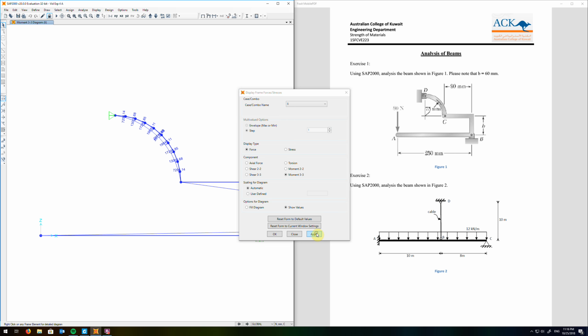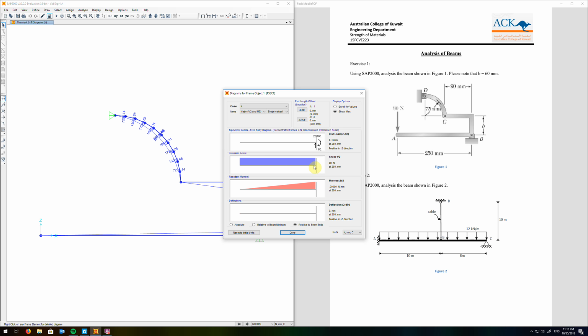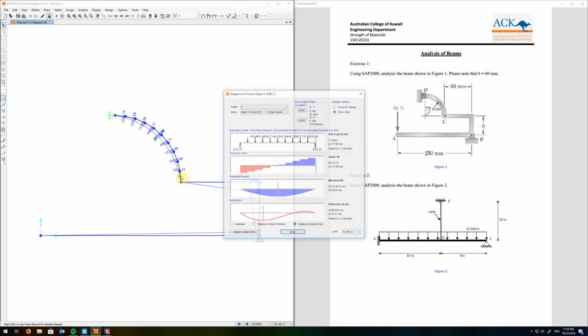So these are the maximum moments. Now since this is a mess, the best choice is to right click on it, and you'll be able to see the maximum moments. On the first member is 20. On this member it is, that's a huge number, 20,000 Newton millimeter, and the maximum is at 54 millimeters. Deflection is kind of funny if you look at it, and it's really interesting.